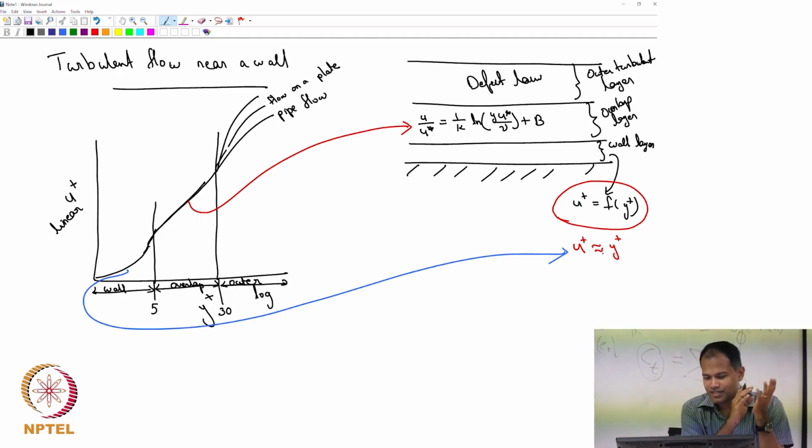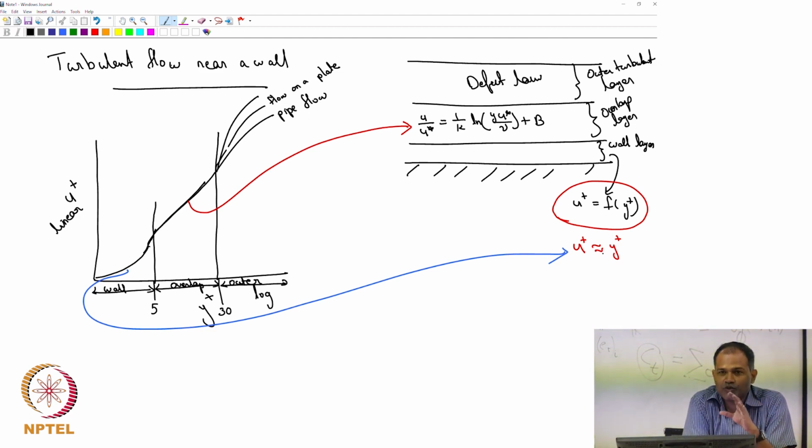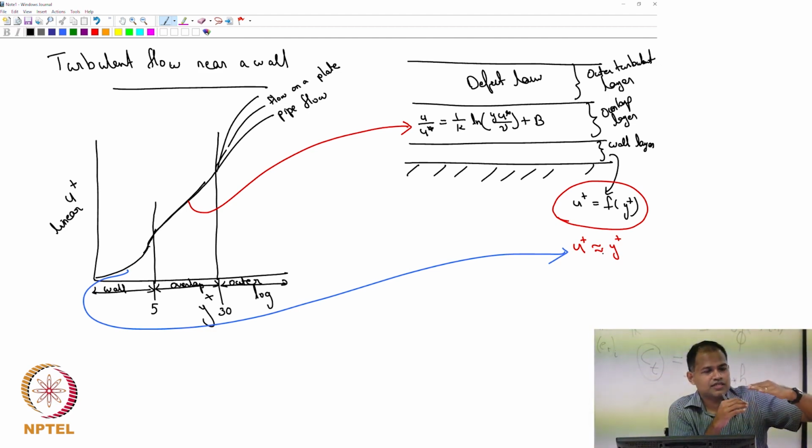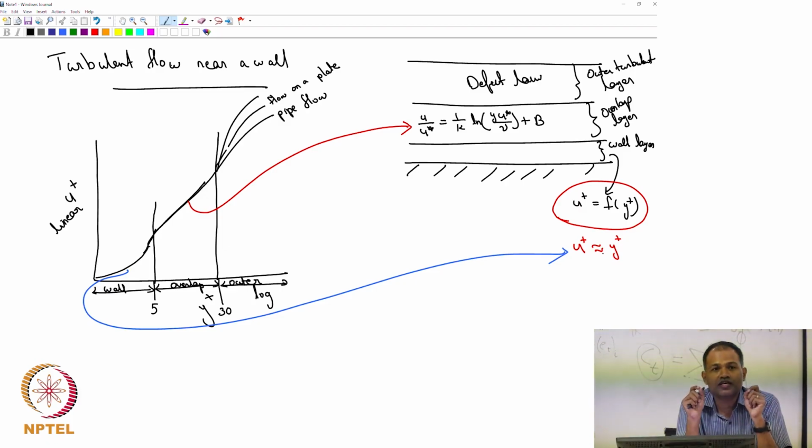The other curvature, I think the flow is never stable. That's why you don't see it. So that is actually the important point. Even though we introduced the overlap layer as something to connect these two regimes, it turns out that the overlap layer is very big and it is a straight line. It's a straight line in the log-linear scale. So the logarithmic law is a very robust law, it turns out, and it spans quite a length, as you see. It's not a small region.